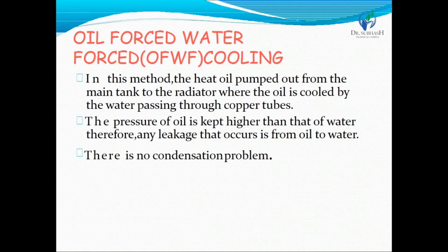The cooling water is taken away and cooled in a separate cooler. The oil is forced and circulated through the heat exchanger by using a pump. This type of cooling is used for transformers having a rating of a few hundred MVA, generally generator transformers.